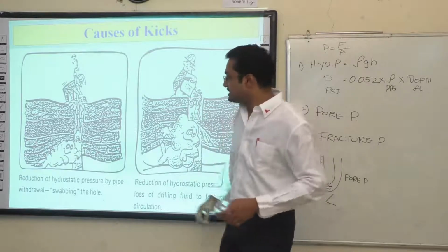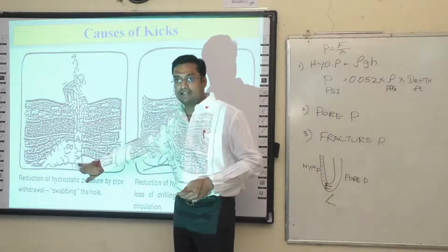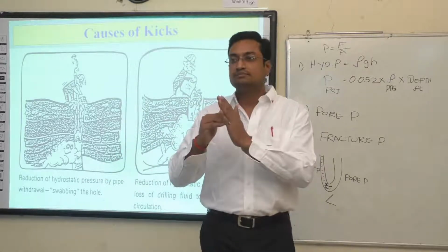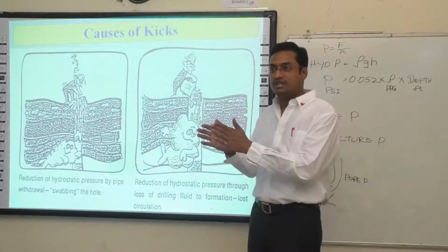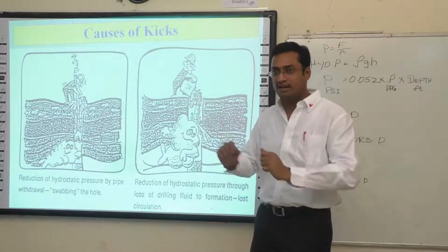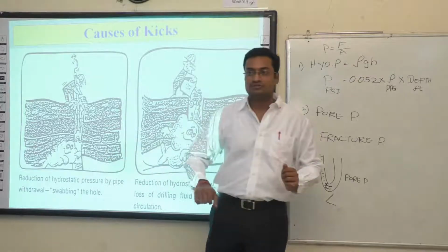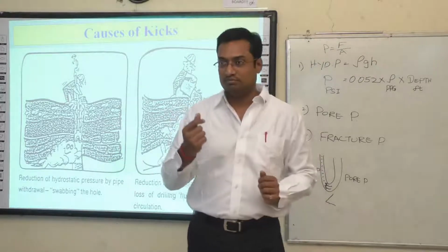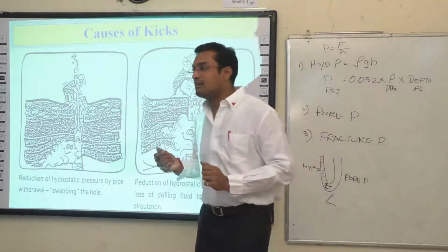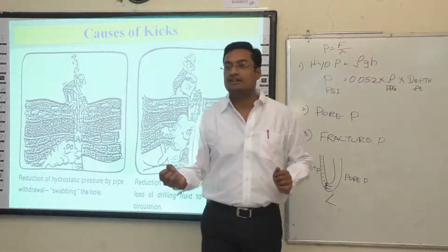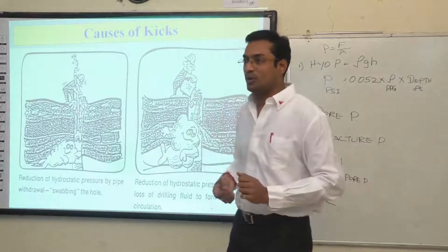That disturbances is enough to create a leak, or for the formation fluid to become more than the hydrostatic pressure, momentarily, temporarily. But once the formation fluid enters into the wellbore, it will start its job. So it will start contaminating the drilling fluid slowly. It will increase the kick volume.